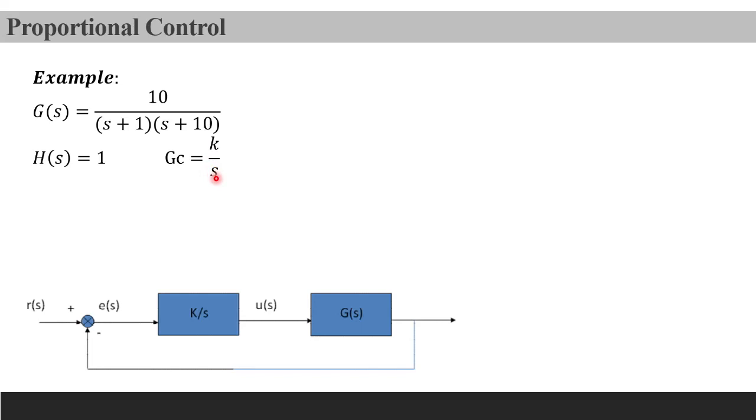In the frequency domain, integration is equivalent to division by s. So we picked a function which is k upon s. Here k is some constant, and since this is not a proportional control, my bad, you can change it to your integral control gain, ki, for simplicity.